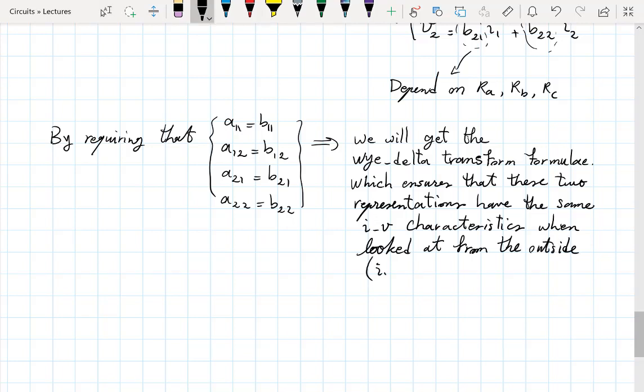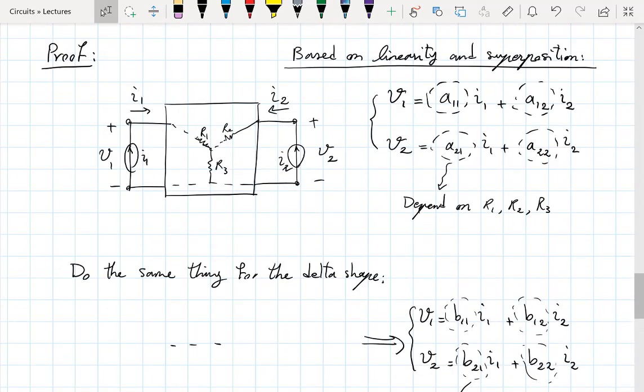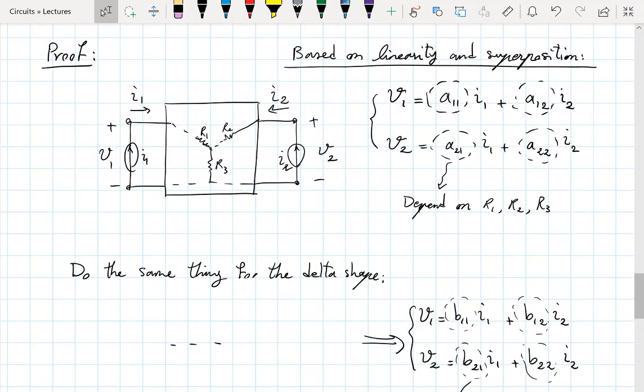That is, they are equivalent. Now that's an exercise in algebra, because how would you do this? Take the first circuit, put two current sources, I1 and I2, here, and solve the circuit. So you've got a couple of loops, some branches, write your KVLs and KCLs and everything. Or do it with superposition.